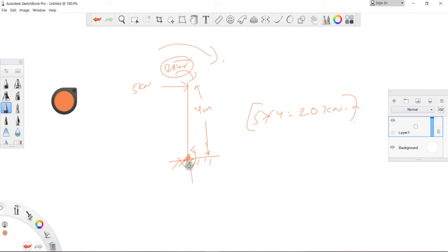The movement at this position is 0, due to which it cannot resist this movement. So we know that if any structure resists certain movement or certain load, the counter movement is induced in that structure. In a secondary beam, what happens is that if these two are our primary beams, and this is our secondary beam,